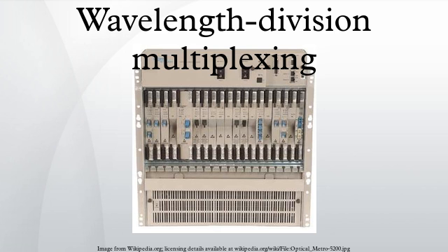Coarse wavelength division multiplexing, in contrast to conventional WDM and DWDM, uses increased channel spacing to allow less sophisticated and thus cheaper transceiver designs. To provide 8 channels on a single fiber, CWDM uses the entire frequency band between the second and third transmission window, including both windows but also the critical area where OH scattering may occur, recommending the use of OH-free silica fibers in case the wavelengths between second and third transmission window should also be used. Avoiding this region, the channels 47, 49, 51, 53, 55, 57, 59, 61 remain, and these are the most commonly used.